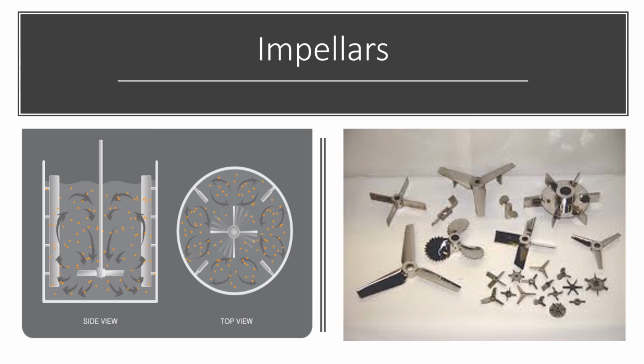If the distance is more, the shear stress experienced by all the particles will not be uniform. And if the bob or the impeller is run at higher speed, it creates some turbulence and it affects the viscosity. So this is how the rheological behavior of materials plays a major role.